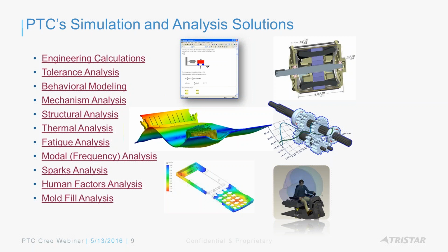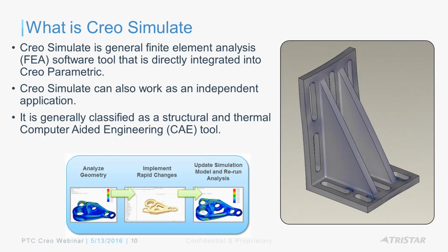And also the mold filling process. That's more from a manufacturing perspective. I would like to see the plastic injection mold filling process. Is there any air trap vents? Are there any red flags that I should know ahead of time on my design? That's something that it allows you to know. It used to be called Plastic Advisor previously, and with PTC's partners it has now changed to mold flow analysis. So that's kind of like a quick listing. Some of you may need some of these, some of you may already be using it, but just a quick overview of all the computer-aided analysis solutions that we have as of today within Creo Parametric, right?